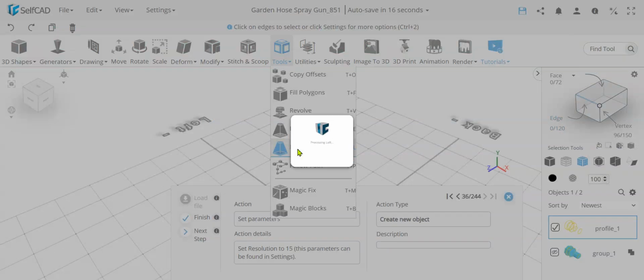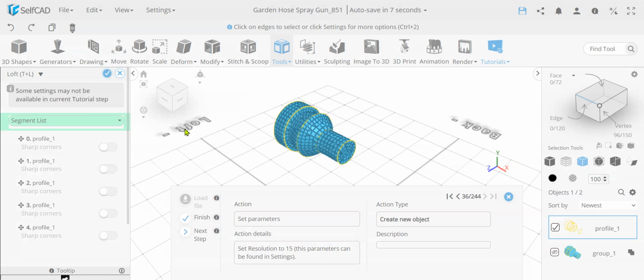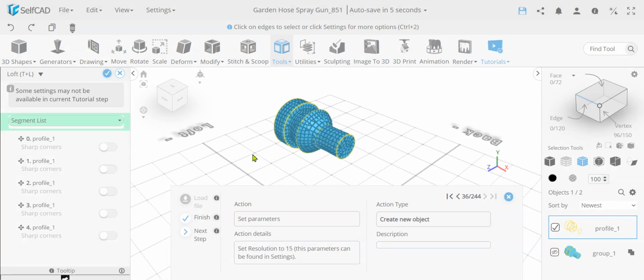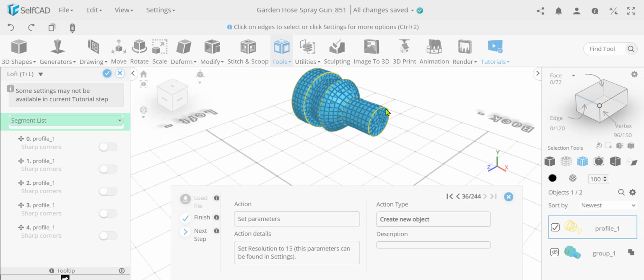So once we enter Loft, here's the interesting thing: Loft basically has a limitation. That's the nature of Loft, because they work with splines. The way they work is, if you have something that is rounded, it must be splines. Meaning, you cannot have tiny edges, like very small edges, a lot of edges, unless you convert them into a spline. You can have edges if they are, for example, longer lines.